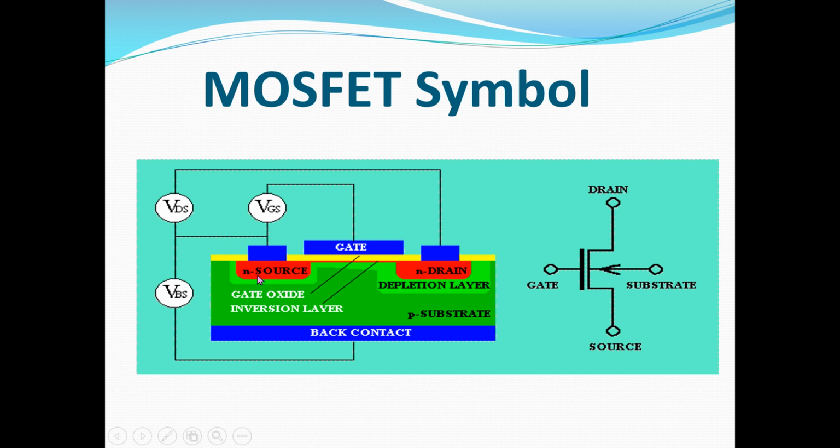So now this is an N channel MOSFET. It's an NMOS MOSFET. That's why these two terminals are of N type. N type impurities have been diffused into the substrate, and then these two terminals have been formed, source and drain, and then the other terminal is called the gate terminal. You can see these are the connection wires which run from the MOSFET to the external circuit.